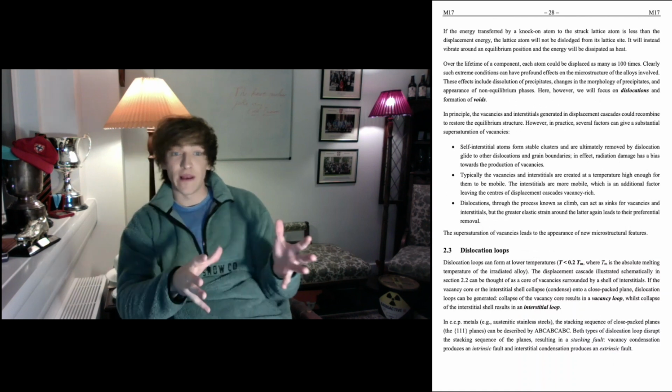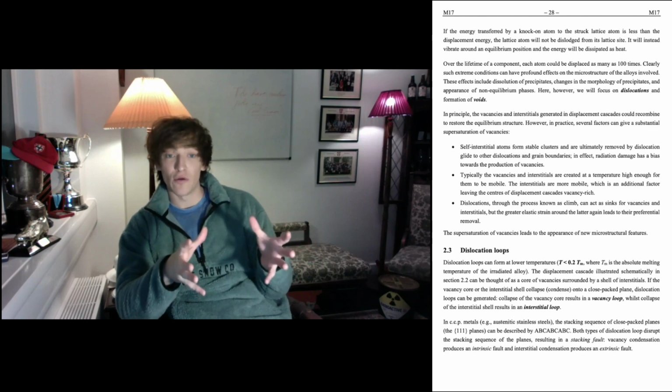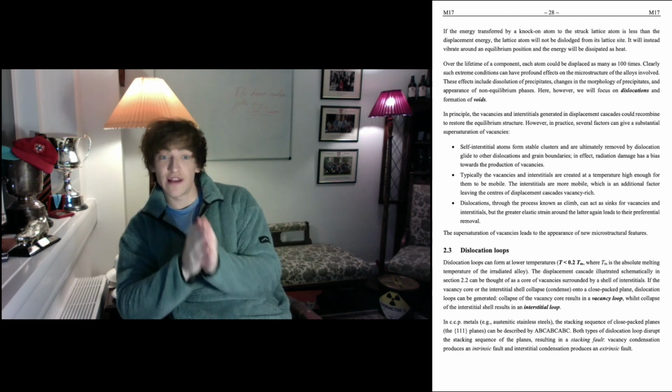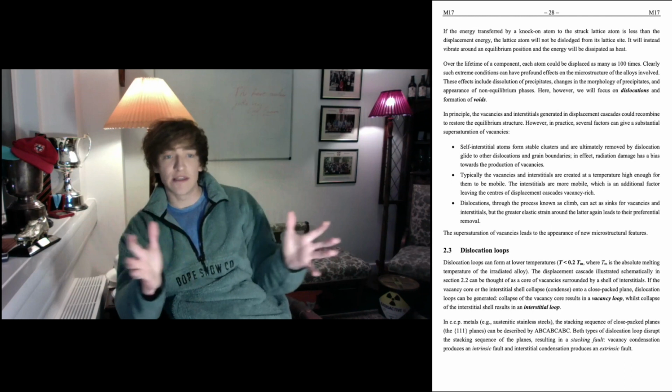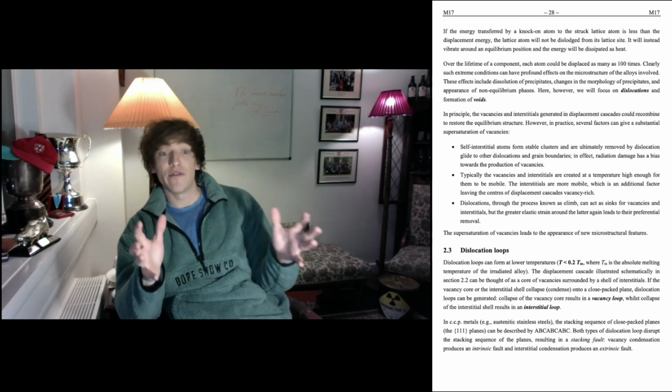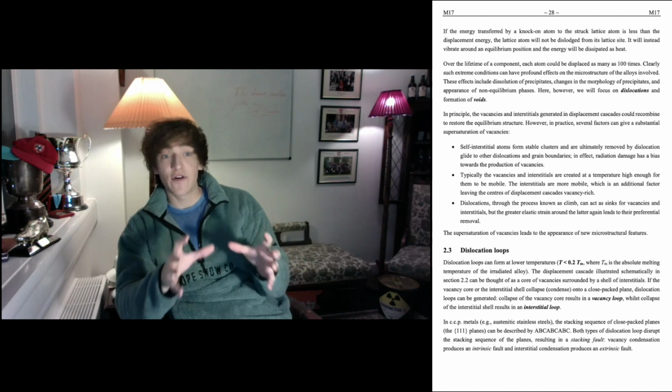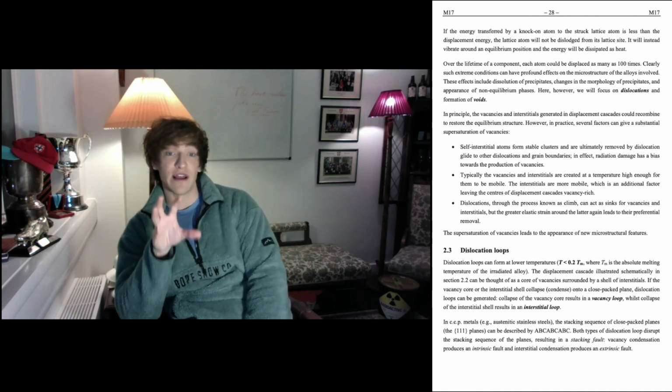Finally, another point is dislocation climb will play a role, as dislocations do act as sinks for vacancies and interstitials, but because of the greater elastic strain around interstitials, they're removed just a little more than the vacancies. And all these points come together and mean that we end up with an excess of vacancies. And like I said, that has a significant role in producing unique microstructural features and radiation effects.